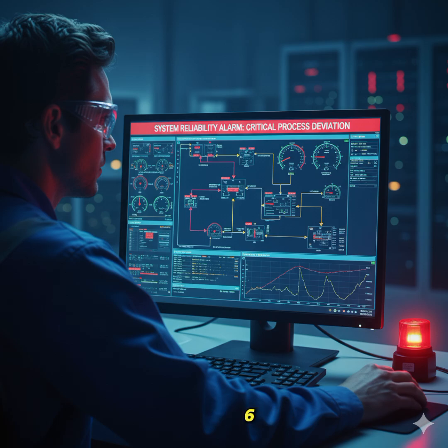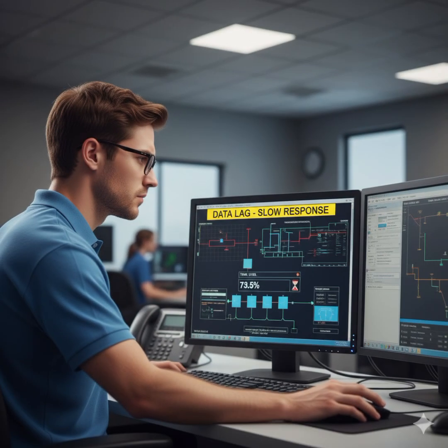Section 6, Modern Trends. Today, the line between SCADA and DCS is blurring. With the rise of industrial IoT, IIoT, and cloud computing, modern plants often integrate both systems. You might find a DCS managing process control inside a plant, while SCADA oversees the same plant's data remotely for